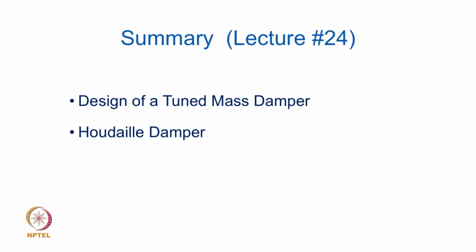And these two lectures basically highlight a possible vibration control measure that you can consider if the system is vibrating with resonant vibration amplitudes. We then had a brief discussion on the automotive Houdaille damper, where the torsional absorber is basically floated in a cavity containing a viscous fluid, and that damper then can be designed to suitably control the torsional vibrations of the automotive rotating shafts.